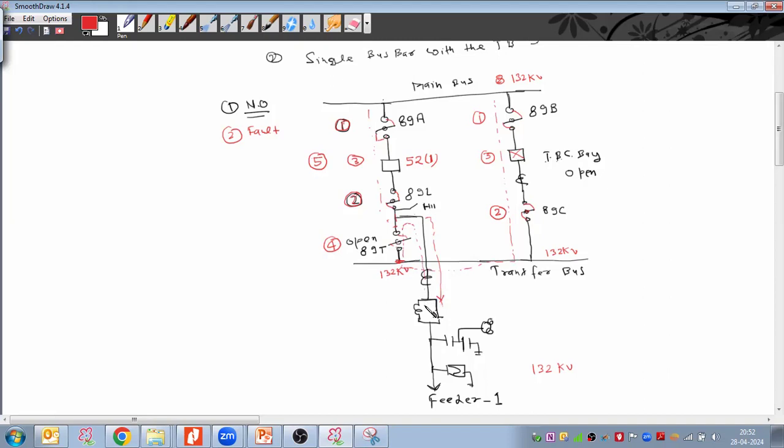Then it is flowing like that. Since they have two parallel power flow directions, thereafter the operator needs to open. So far they have been closing all the switchgears, now they are coming to open. The operator now needs to open the 52 circuit breaker. Once this circuit breaker is open, thereafter they can open the bus isolator 6, and then they can open the line isolator 7.